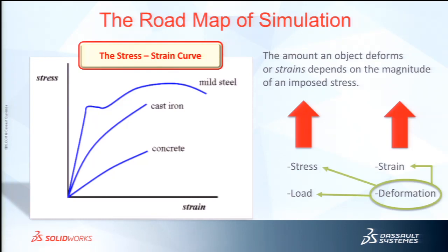Well, it's because it's something that we can easily measure, because the strain is really just the amount of deformation. We can take a ruler or a set of calipers or a yardstick, depending on how much stress there is, and actually measure the deformation of it. So if you increase the loading, you're going to increase the deformation. By increasing the loading, you're going to get more stress and more strain. Even though they're 2 separate columns, they're all related. And they're all solved for by something we can easily measure, and that is the displacement.